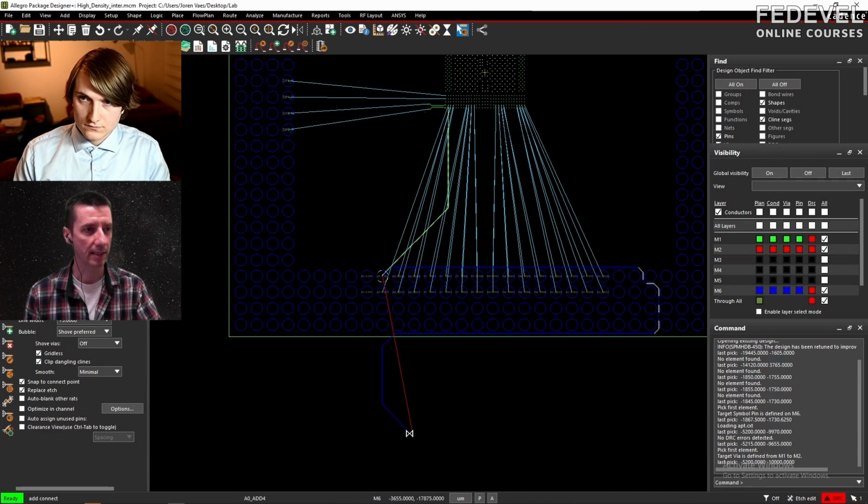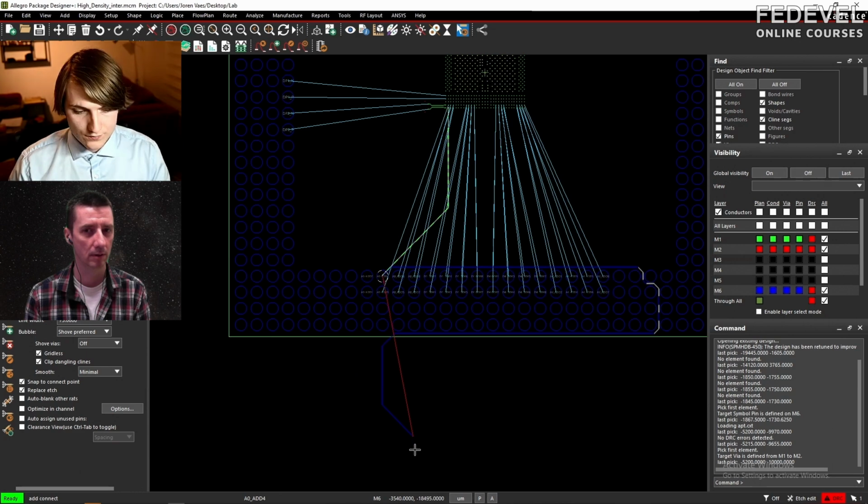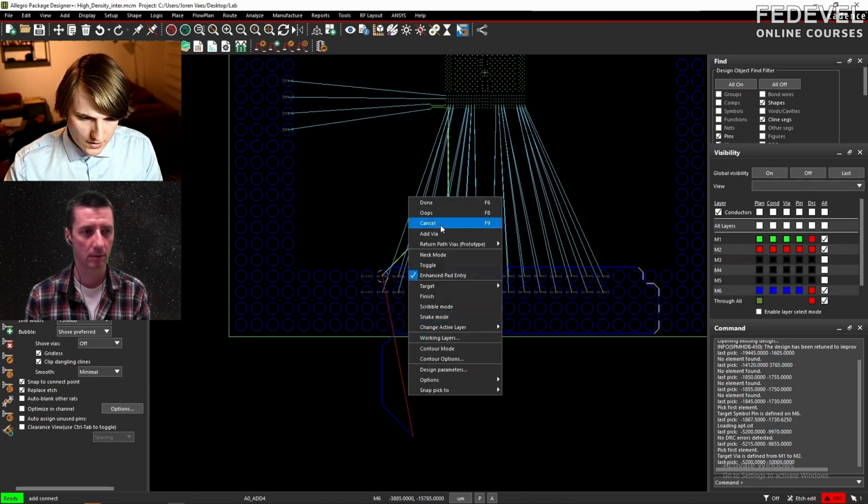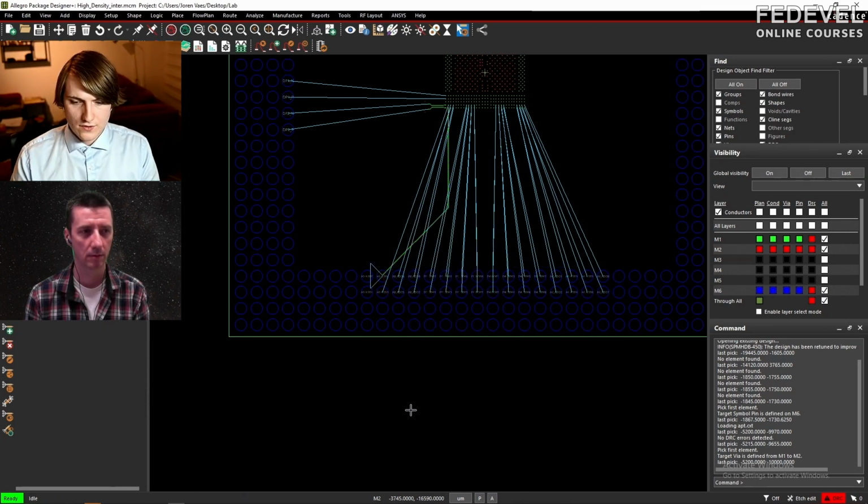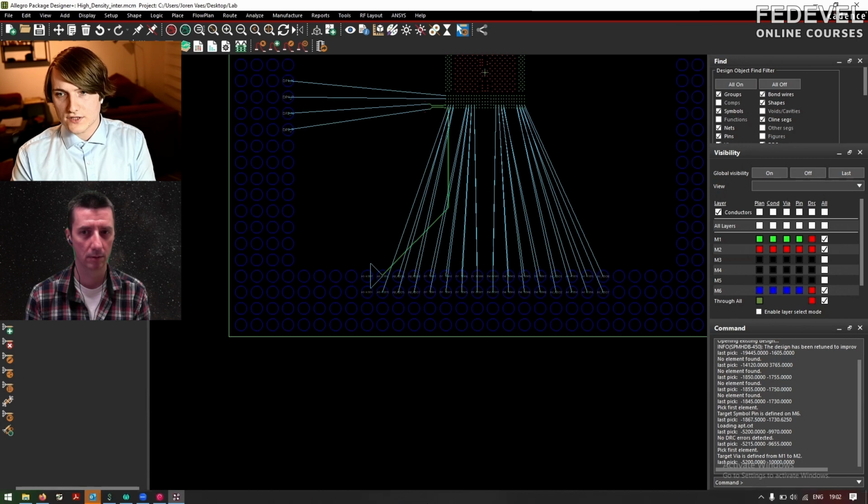So this package, is it based on kind of PCB? Sometimes it is. I think you can say that you have three big groups. You either have your old school package, where you have a DFN or a QFN, and these are what they call lead frames. This is a standard thing that you buy off the shelf. They place the chip inside, and then they use bond wires to connect the pins, and then they close it up. So that's the bond wires option.